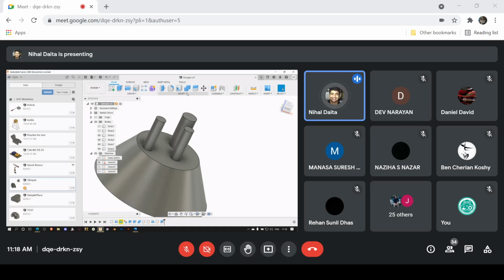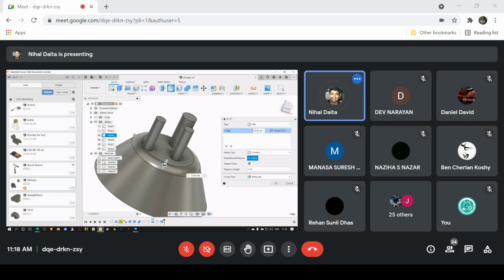there's this, as you can see in the modify tab, right? I haven't shown you this much. Fillet is basically the same fillet as in 2D, but in 3D, it just goes in a 3-dimensional direction. So if I click fillet and if I click here, right, you can see it will smooth off the edge. You can definitely use it. I'm not using it here. I'm just showing you how it goes. You can just pull it or you can give a proper radius.